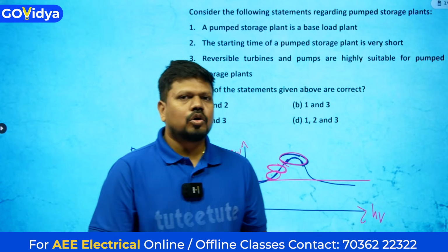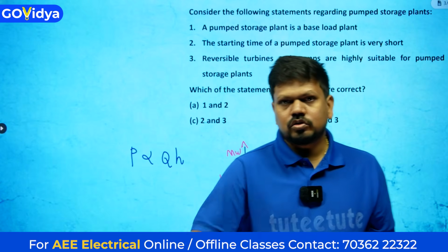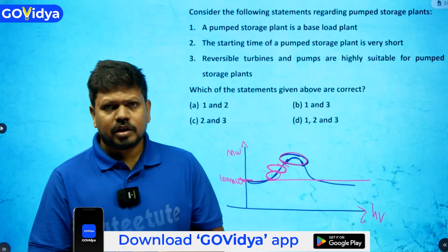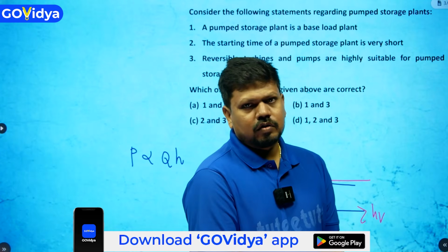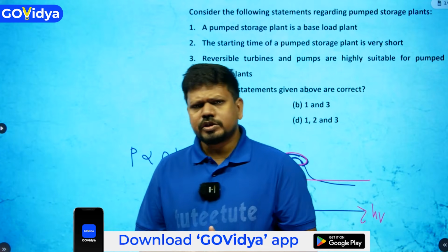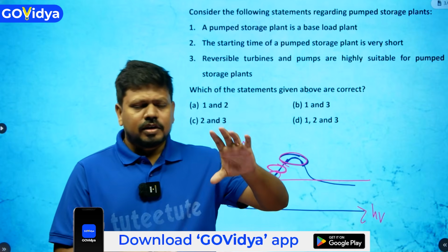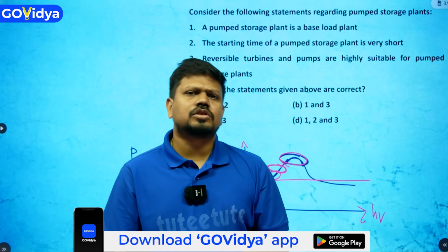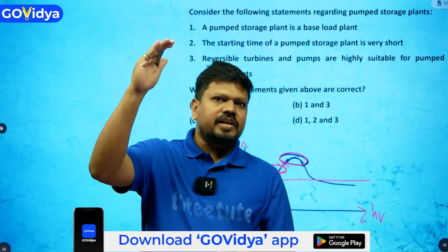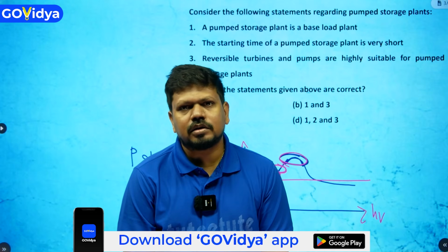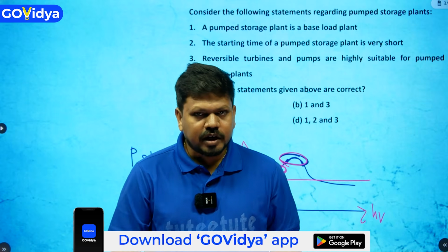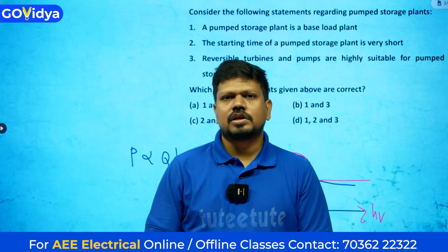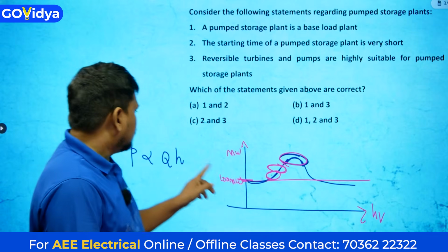If you know about the Srisailam power plant, we have 2 plants in Srisailam. One is considered the AP one, another one is the Telangana one. Anyhow, you observe there, the turbine will be going to the downside of sea level. That means instead of increasing the dam height, we are decreasing the turbine height, making a negative height. So the head will be increased, so power output will be increased.